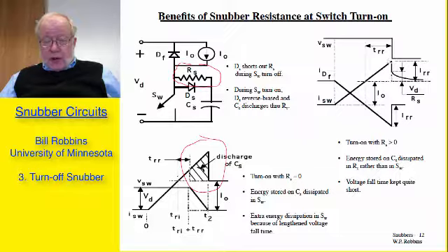The current drops from IRR plus I naught to some intermediate value and then decays the rest of the way back to I naught. And that is with a finite value of R sub S. The voltage fall time is then kept significantly shorter. It's not extended over the range that I indicated earlier, from here to here, because of the extra energy being discharged into the switch.